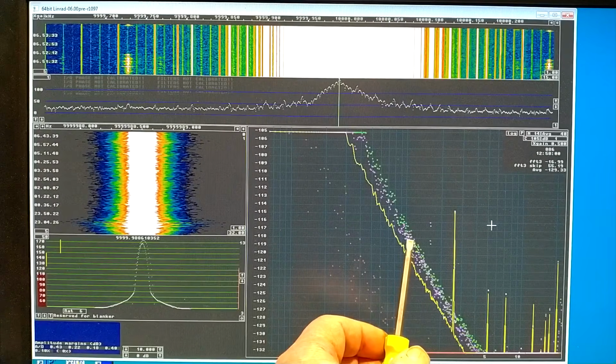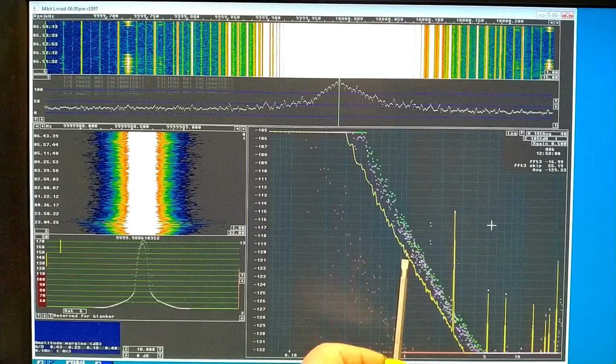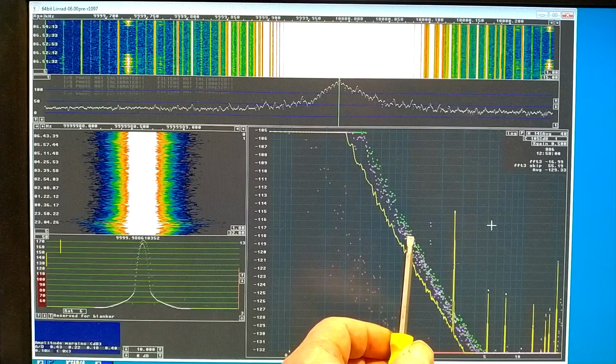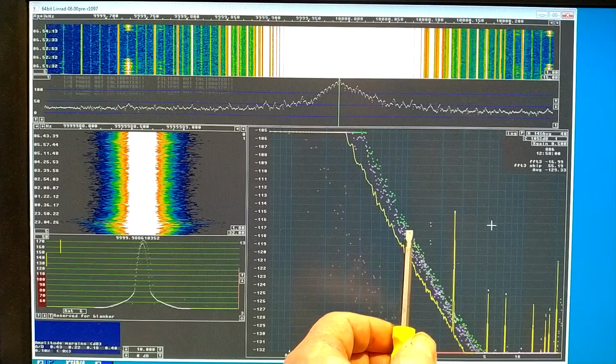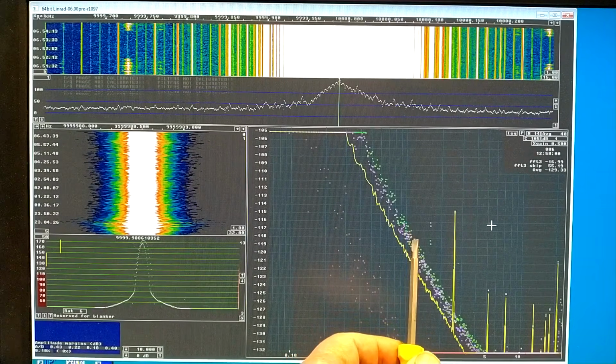My test oscillators, the uncorrelated signal, is about 2 decibels higher here, but it contains the noise of my reference oscillators as well as the noise of the Wenzel oscillator. And since it is not as much as 3 dB above, it means that these oscillators are better than the Wenzel oscillator. Not much, but a little bit.